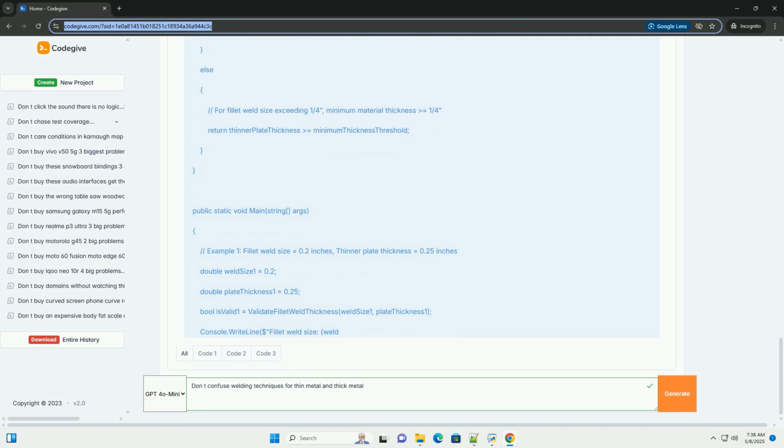Welding parameters: amperage, voltage, travel speed, gas selection, and wire feed speed. Preventing and addressing common issues: burn through, distortion, porosity, and undercut. Code considerations: specific requirements based on metal thickness and application, for example AWS, ASME. Code examples, illustrating how code standards dictate material thicknesses and acceptable welding practices.